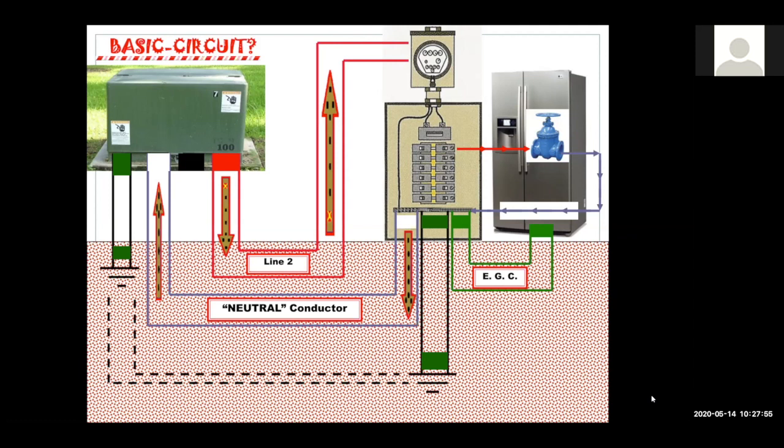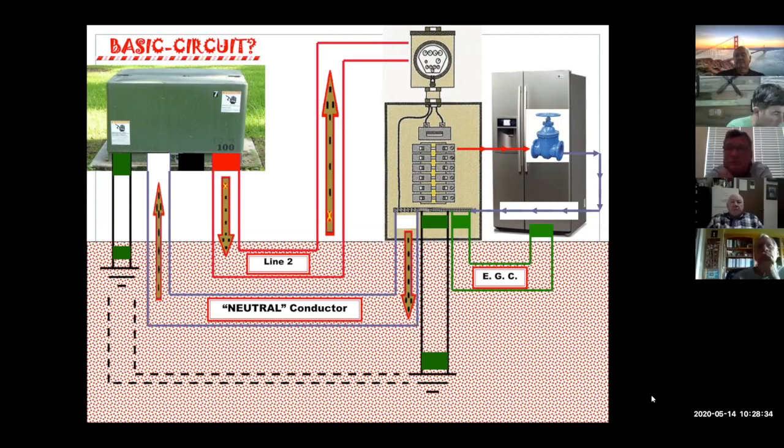Oftentimes it's said, and we're supposed to understand, that a load, and remember now, a load is any appliance, any equipment that you're supplying, is drawing current. All right. How many amps is it drawing? Well, look at it a little bit differently. It's not drawing anything. Drawing, pulling, sucking the current. No, it is controlling the amount of current that goes through that load. So loads don't draw, pull, or suck. They control the amount of amperage that goes through and completes the circuit.